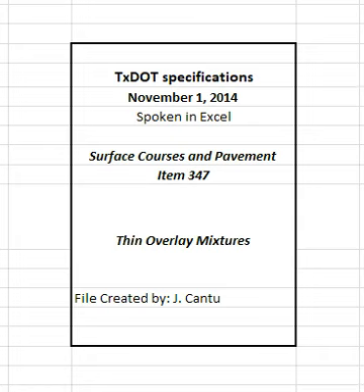4.9.4 Exempt production. When the anticipated daily production is less than 100 tons, all QC and QA sampling and testing are waived. The engineer may deem the mixture as exempt production for the following conditions. Anticipated daily production is more than 100 tons but less than 250 tons. Total production for the project is less than 2,500 tons. When mutually agreed between the engineer and the contractor, or when shown on the plans.